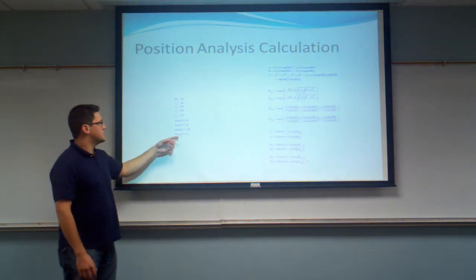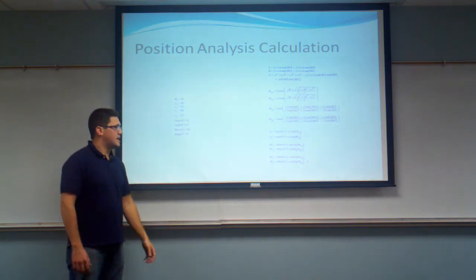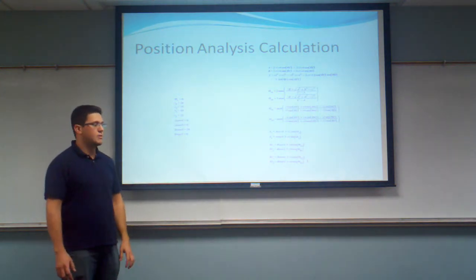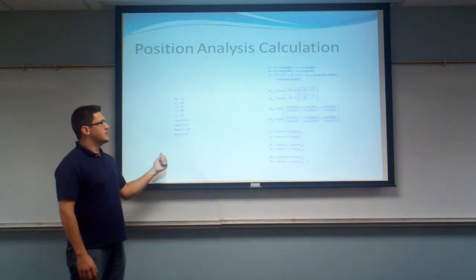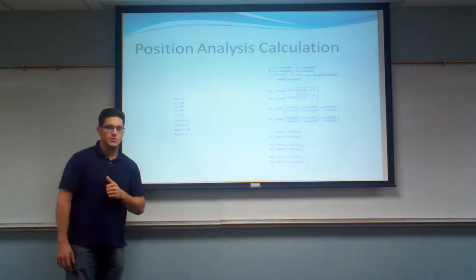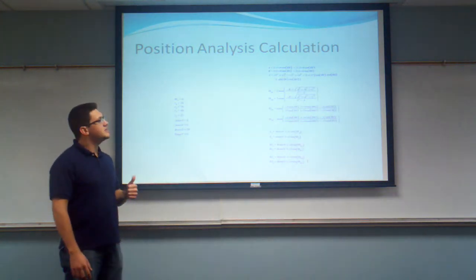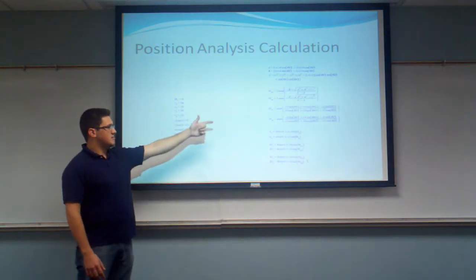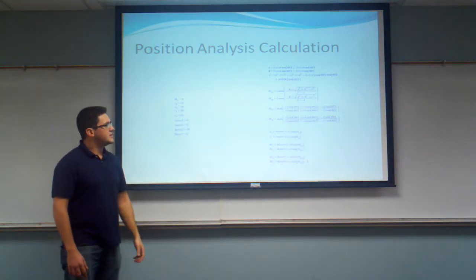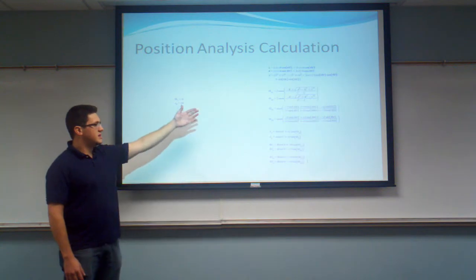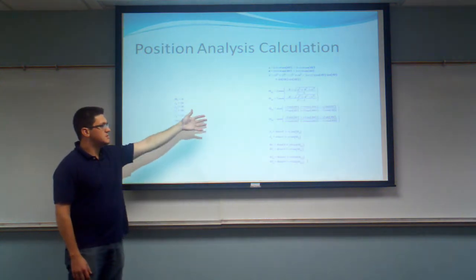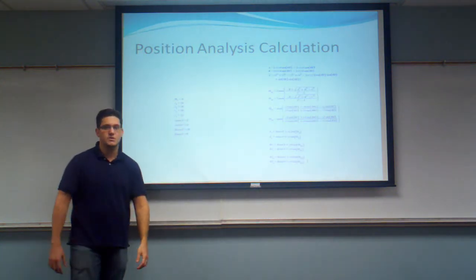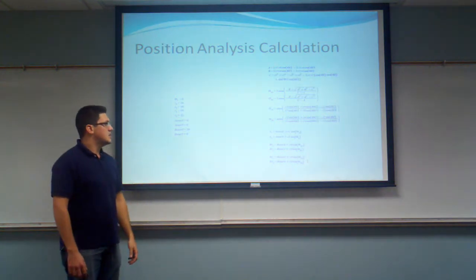Theta 1 was set equal to 0 because the y-axis was 0 for both poles A and B. And then what we did is we used theta 2 between 1 and 360 degrees, using these equations that you see here on the right to calculate theta 4 and theta 3. Because there were 2 possible solutions for each, we ended up with 2 different closures of the mechanism.